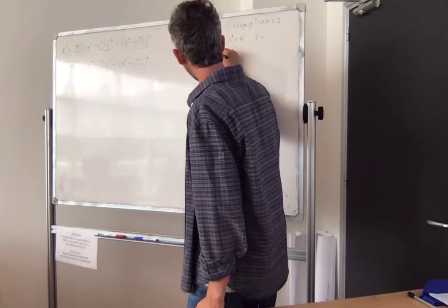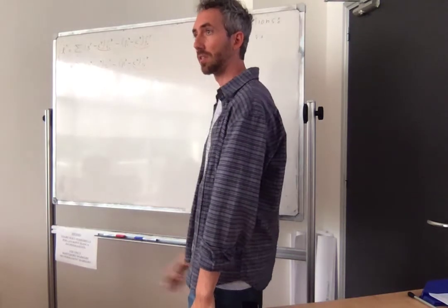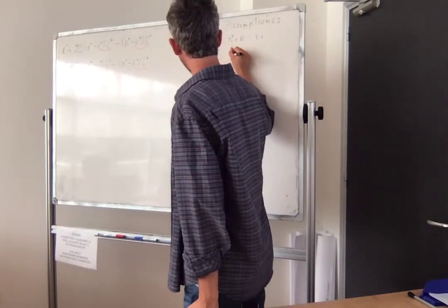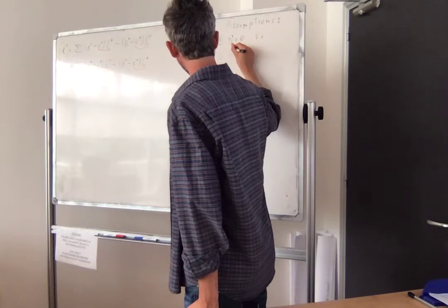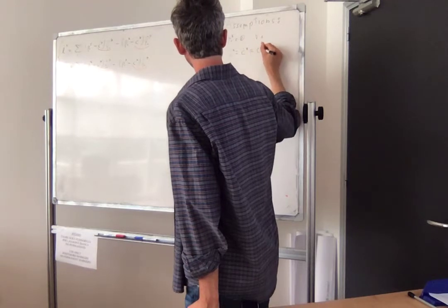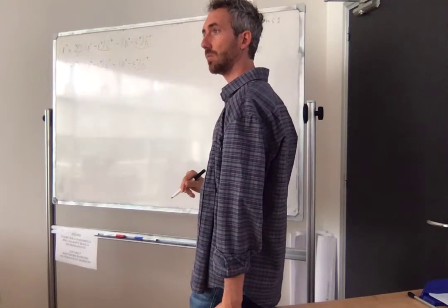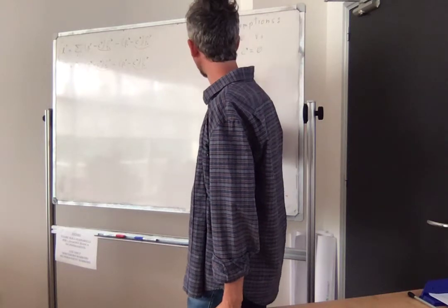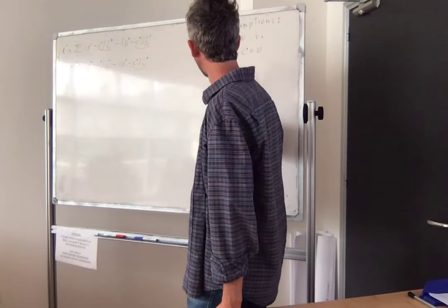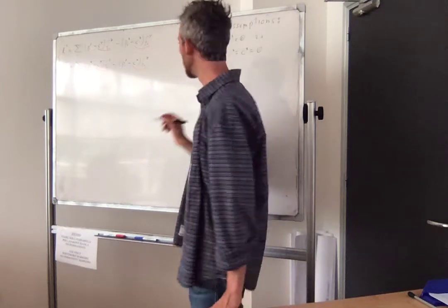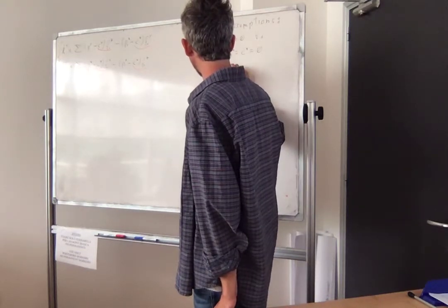And then the second assumption is that since I'm walking on a flat ground, also the height of my center of mass is going to be constant. So C double dot z is going to be equal to C dot z, which is going to be equal to 0. Third assumption, which is actually not really needed for making the equations linear, but it's typically taken anyway, is that my angular momentum is going to stay at 0.